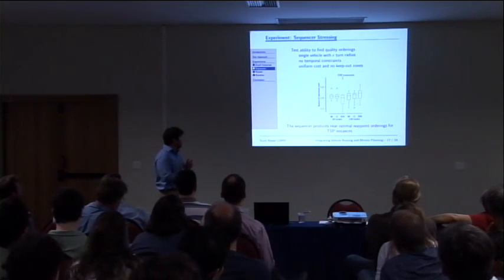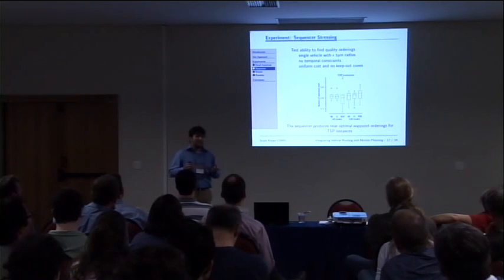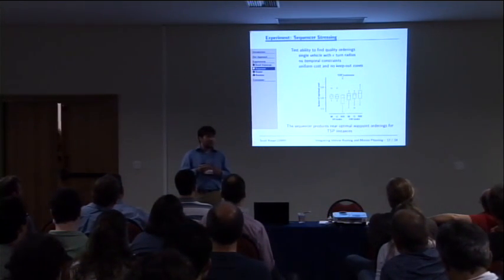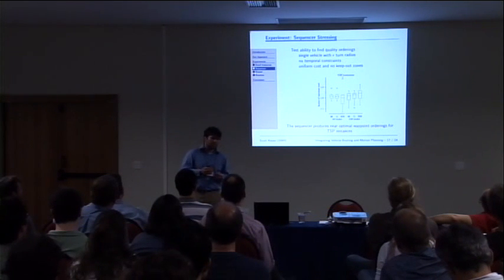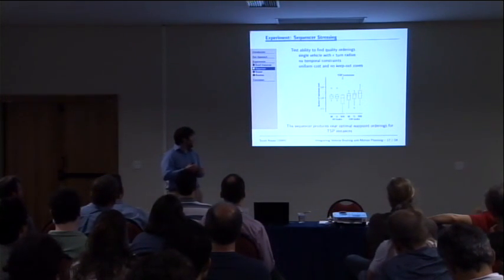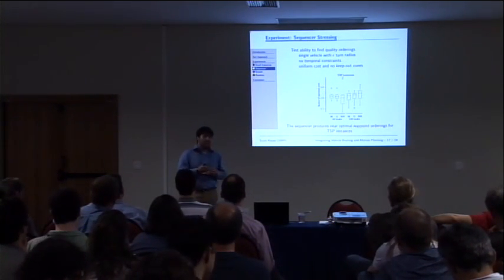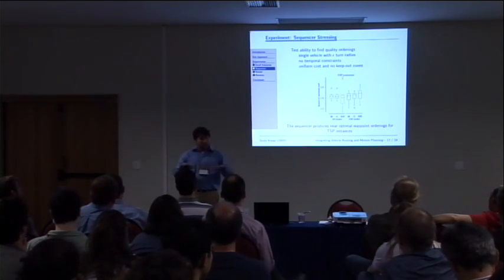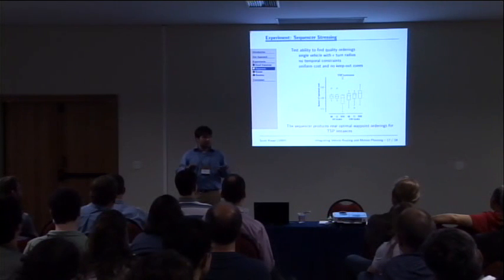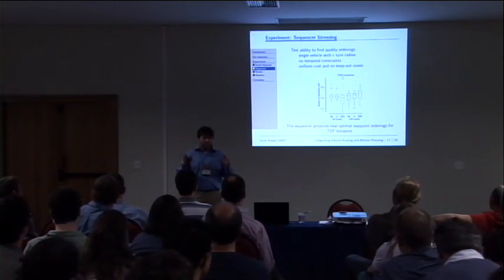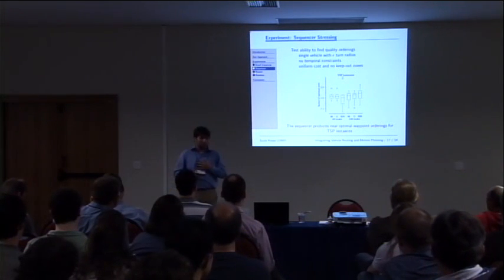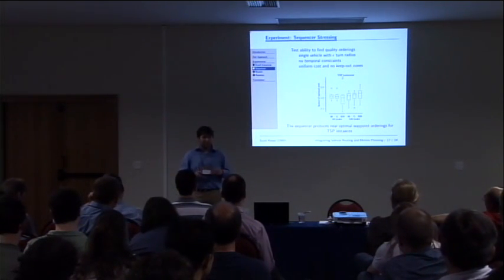So we took a look at the sequencer, and we constructed these TSP-like instances to test the ability of the sequencer to find good orderings among these waypoints. We constructed these as a problem with a single vehicle, epsilon turn radius, no temporal constraints, and we've spread a uniform cost with no keep-out zones across the entire map. So pretty much a standard TSP, but we'll have to actually route. But epsilon turn radius means we can pretty much connect straight lines.